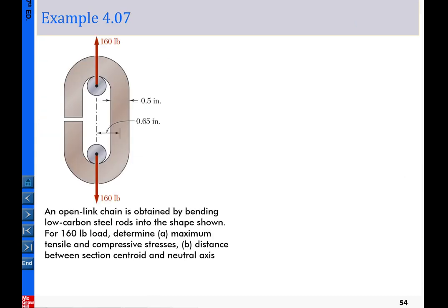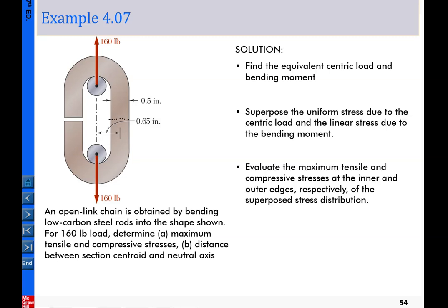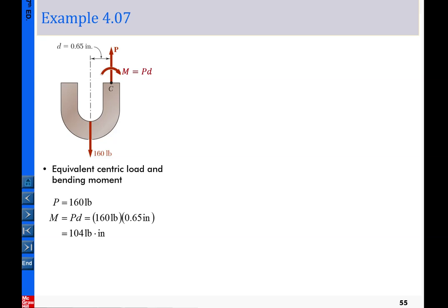Now we can take a look at one real situation, a numeric example. For this case, we want to determine the maximum tension and maximum compressive stress. So we pick the section here, and then we decompose it just like we did before. From that section, this is the applied loading. Using equilibrium of the forces in the vertical direction, P should be equal to 160 newtons.